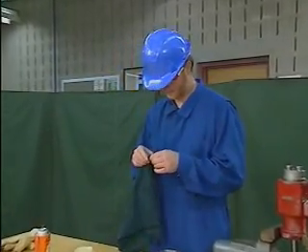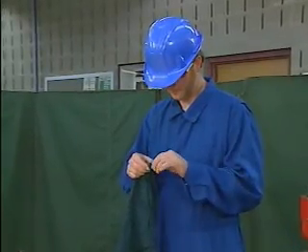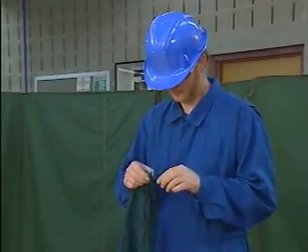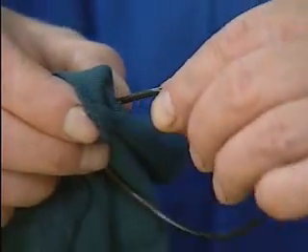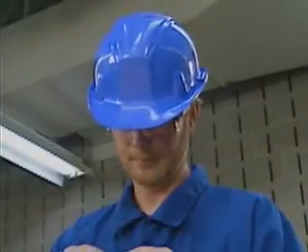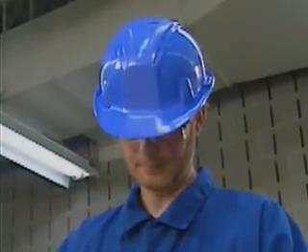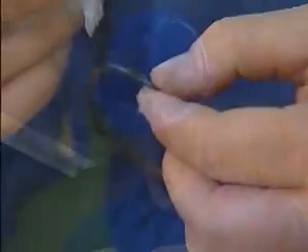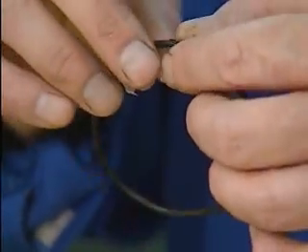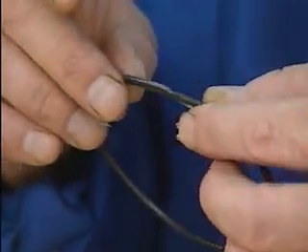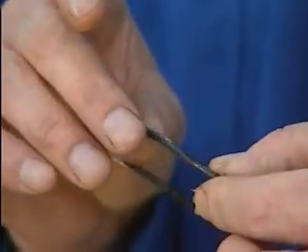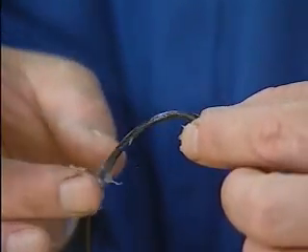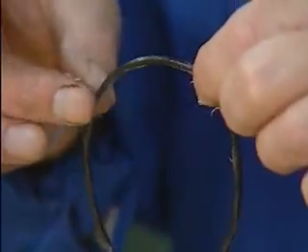This O-ring is not damaged, so the mechanic can continue to the next step, which is lubricating the O-ring. Many O-rings, due to their rubber composition, have a tendency to stick or bind to metal sealing surfaces. Lubricant is often used to allow the O-ring to seat more easily during installation. The lubricant that's used must be compatible with the fluid in the system and with the material that the O-ring is made of. If the wrong lubricant is used, the O-ring could react with the lubricant and the O-ring could be damaged.